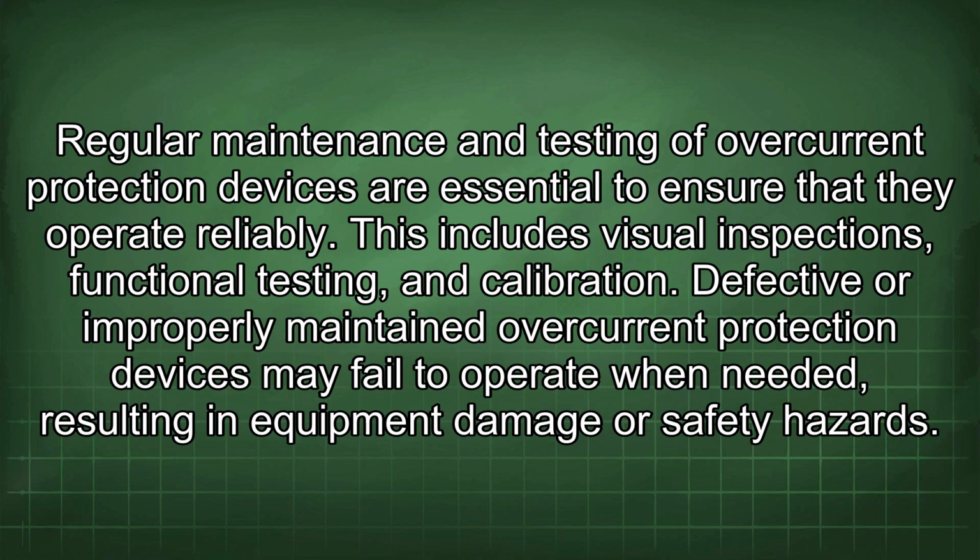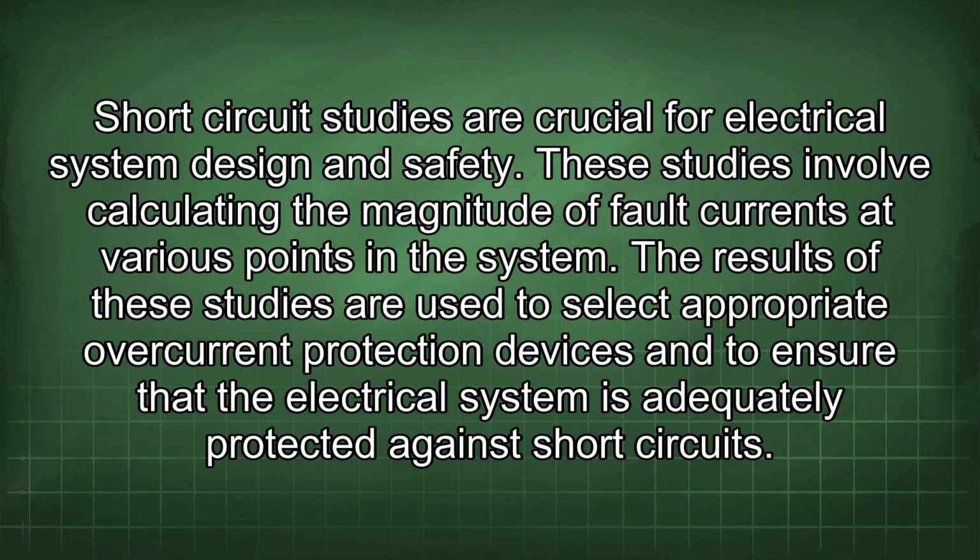Defective or improperly maintained overcurrent protection devices may fail to operate when needed, resulting in equipment damage or safety hazards. Short-circuit studies are crucial for electrical system design and safety. These studies involve calculating the magnitude of fault currents at various points in the system. The results are used to select appropriate overcurrent protection devices and to ensure that the electrical system is adequately protected against short circuits.